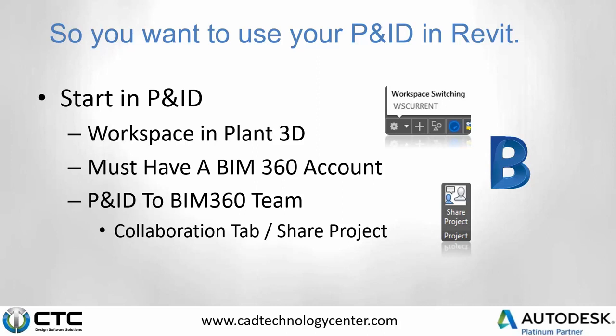What's nice about it being a cloud shared project is that you can gain access to a multitude of different platforms. And of course, we'll be getting into the BIM 360 team application a little bit here, and show you the process as it goes through BIM 360 team and into Revit. Where you would go inside of the PID environment would be the PID collaboration tab, and then Share Project is the command. And again, I'll be walking through that here in just a moment.